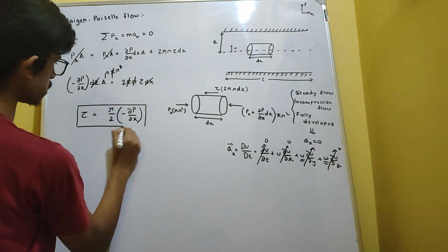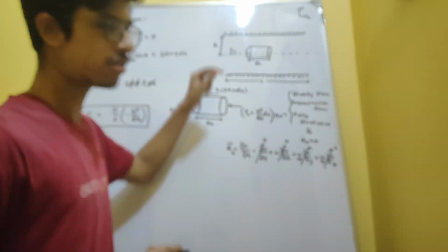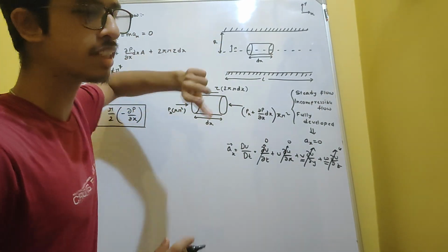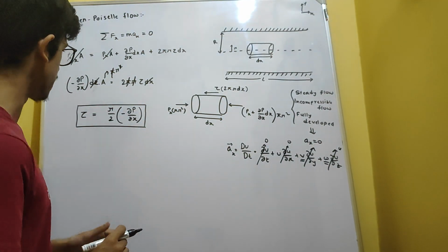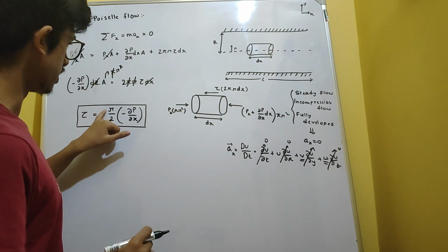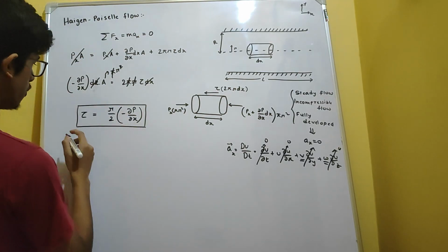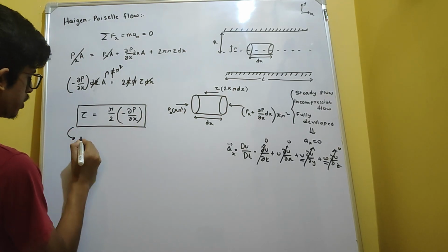So from this equation we can observe how the shear stress is varying with the r direction, or with the y direction, that is, radially how the shear stress is varying. So radially you can observe that shear stress is varying linearly, since r is to the power 1. So where will the maximum and minimum values of tau occur?